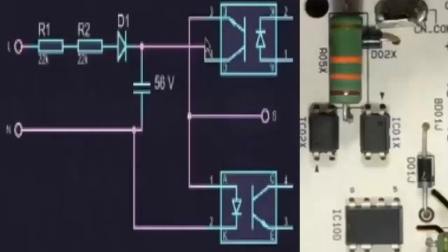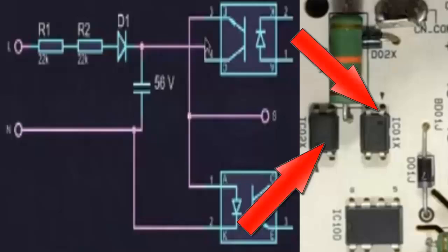12. Verification of the communication circuit. You can also locate the communication circuit by looking for the pair of optocouplers. Check the values of resistors, electrolytic capacitors, and diodes in this area.